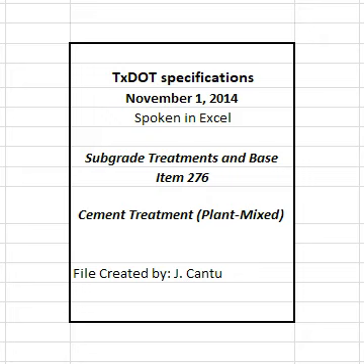5.4 Ton. Cement treated base will be measured by the ton, dry weight, in vehicles as delivered on the road. The dry weight is determined by deducting the weight of the moisture in the material at the time of weighing from the gross weight of the material.